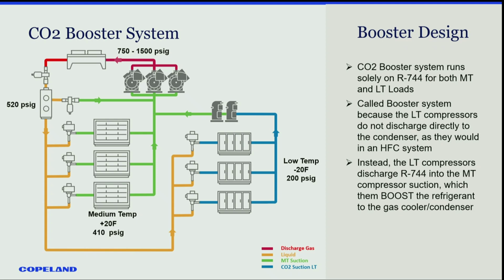Now you get to the high pressure valve, which is nothing more than an electronic expansion valve that's rated to 2,000 pounds of pressure. As an expansion valve, it expands that fluid to a lower pressure, because we need a lower pressure in the flash tank, just like we need a lower pressure in our evaporators. So we need an expansion device to do it, a specialized expansion device.